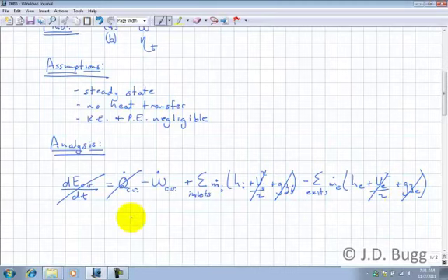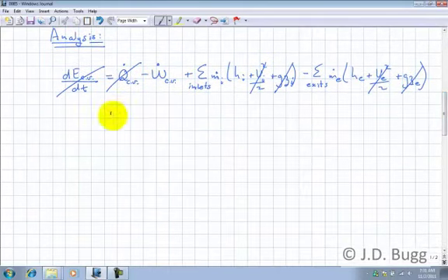The other thing that I'm going to do before I copy this equation down again is divide through by the mass flow rate. There's only one inlet and one exit, so these mass flow rates are common. When I divide by the mass flow rate, I get the work per unit mass. So this becomes the work of the turbine is equal to h1 minus h2, using the numbering that I labeled my diagram with already. We need to get these two enthalpy values to get the work. We already know that at point 2 the state is fixed, so let's do that one first.